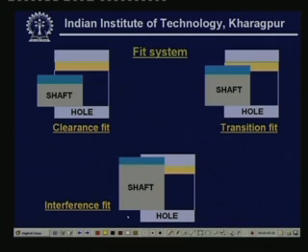So, in this case, the hole can have any dimension which starts from here and which ends over here, meaning anything starting from here to here up to this much. So, as per our definition, we consider this to be the tolerance zone, and this is what we are considering the minimum size, and this is the maximum size.